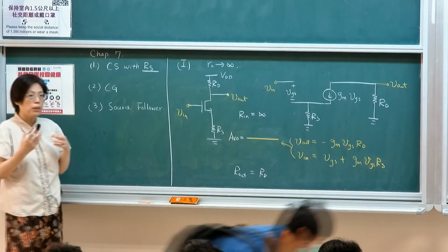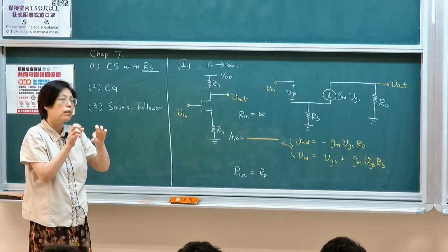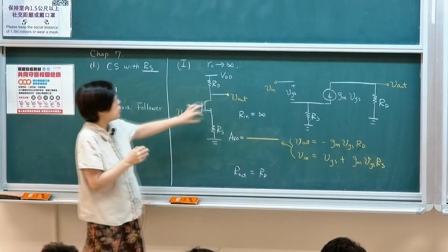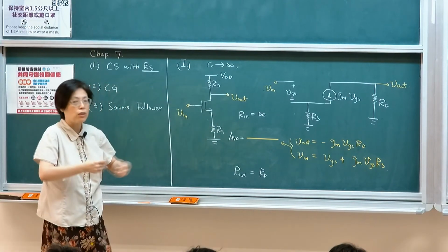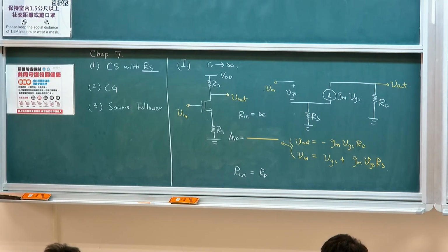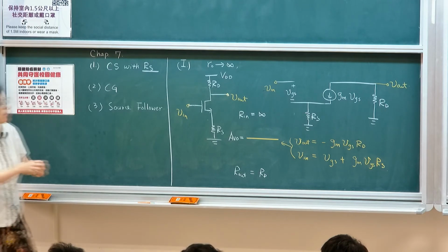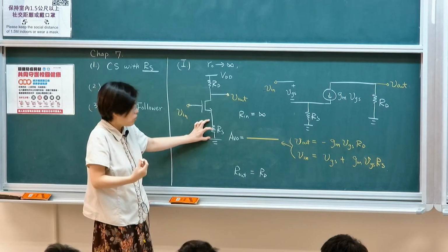The controllability of a transistor is by transconductance, because by modulating voltage, you modulate the current. This will then lessen the effect. It's like, as I said, a water-saving faucet. You add a sort of rubber band around the faucet so that it will be less sensitive when you turn the knob. So that's the basic idea of having a source degeneration circuit.